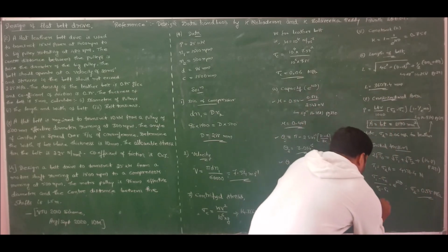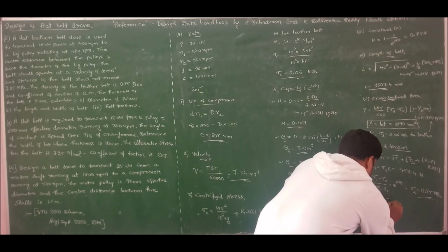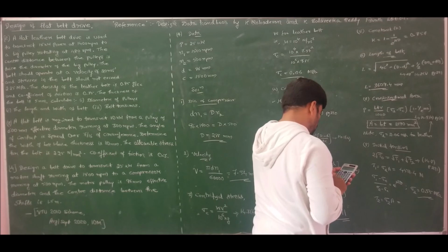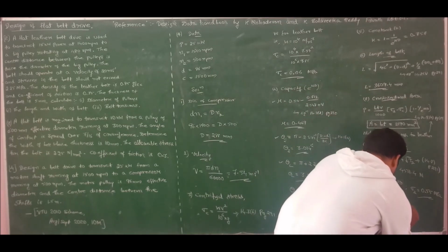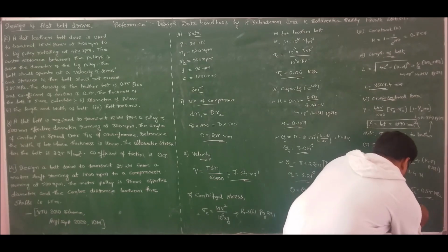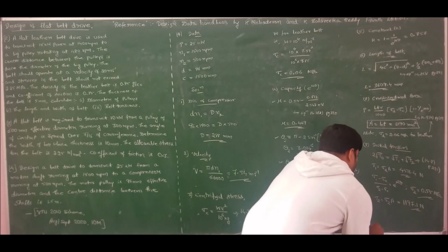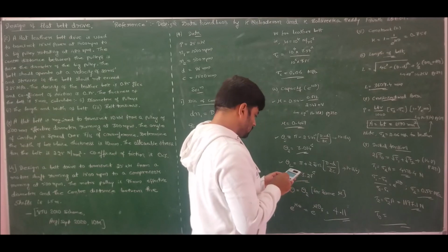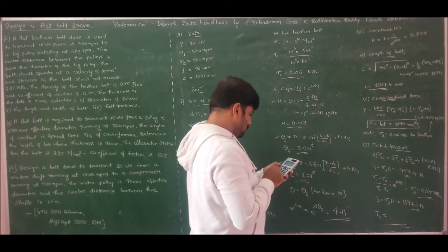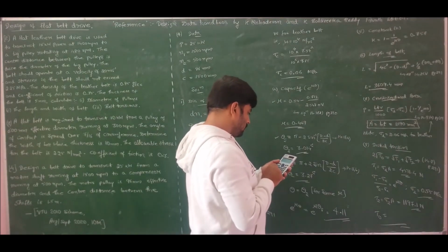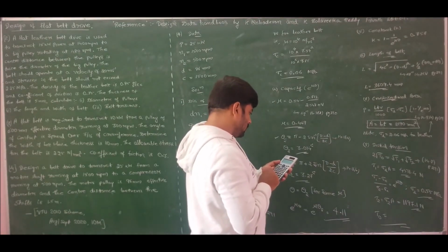So therefore, I can find the value of T2. T2 is sigma 2 times area. Area is 2190, so T2 is 1197.1 newtons. So we know T1 and T2. Therefore, the initial tension T naught is root of T1, 4511.4, plus root of T2, 1197.1, divided by 2.